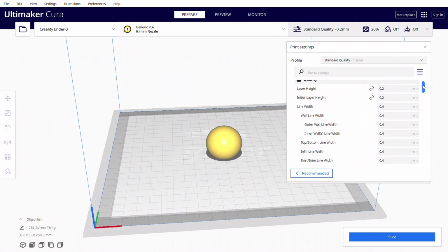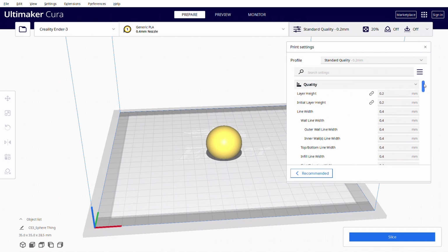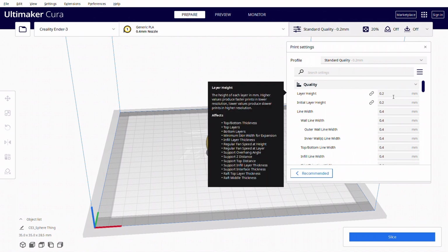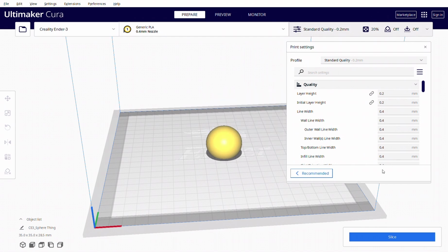And today I want to walk through each of these different items and talk about some things that they may correspond to as far as their settings or other things that may affect. Layer height is a big thing that I will play with in all my different prints. I do have some standards. 0.2 is typical for a lot of my items, but if I do want to go smaller, I can adjust this to 0.12, 0.08, depending on what I want to set this layer height.